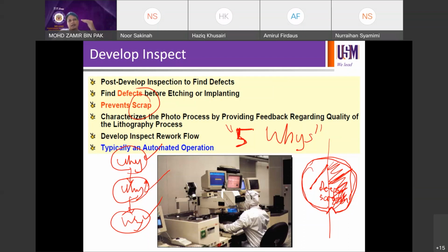Okay. CD is out of spec. Why is it so? Because the robot arm is not placing correctly. Why is it so? Then the robot arm's theta is off. Why is it so? Like, why is it so. They want to answer that, but to be more accurate, why is theta off? Then you start opening the doors and running the robot arm on a test wafer to see how much the theta is off, why is it off, what could lead the theta to be off?